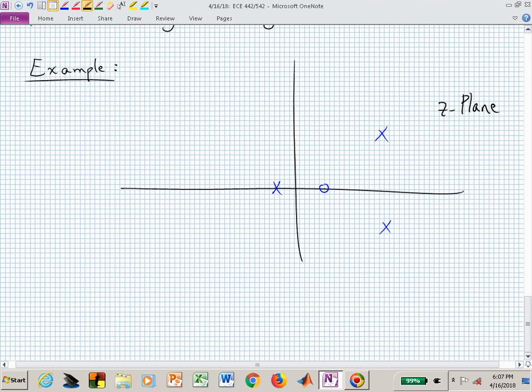Let's say that's the pole-zero diagram, and what I'm really wanting to learn from rule number 4 is, if I went away from this to 30,000 feet, what's the 30,000-foot view of this pole-zero pattern? How can I approximate the behavior of these 3 poles and 1 zero? What do they really look like if I'm really far away? That's what the asymptotes are going to provide me with, is that information.